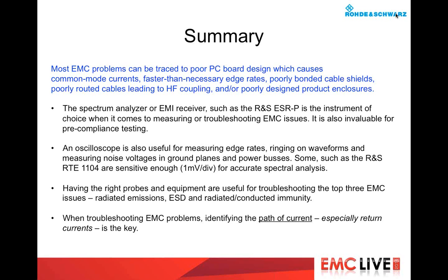And you always want to consider the path of current. Digital designers don't always understand that it's the current that's important, not the voltage. And typically the return currents are usually undefined when you design your circuit board, and if the return currents have an undefined path, you're just asking for trouble. So that's the end of the talk.